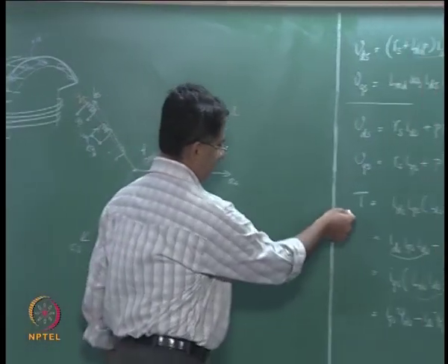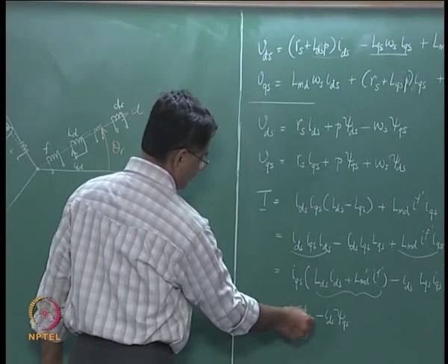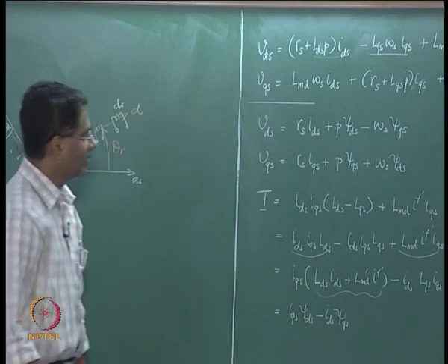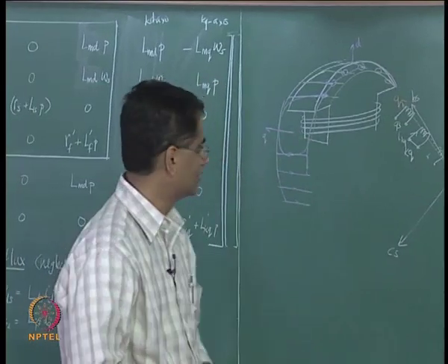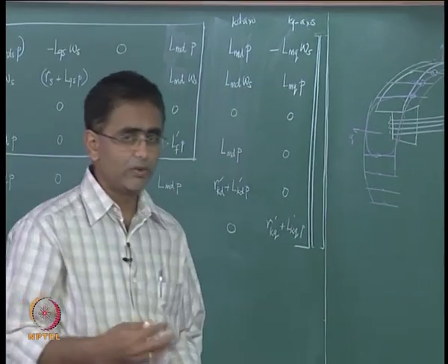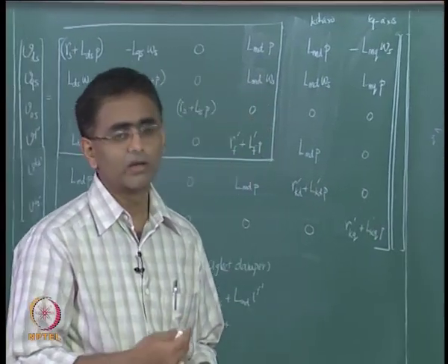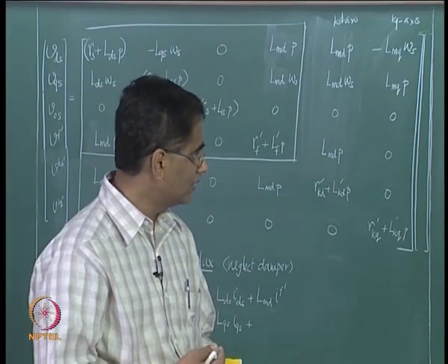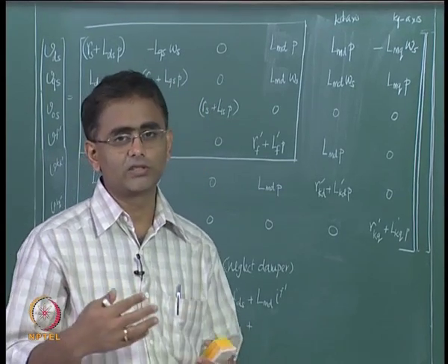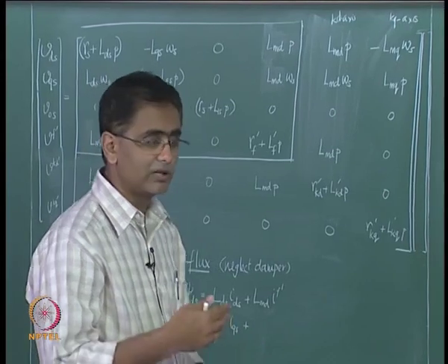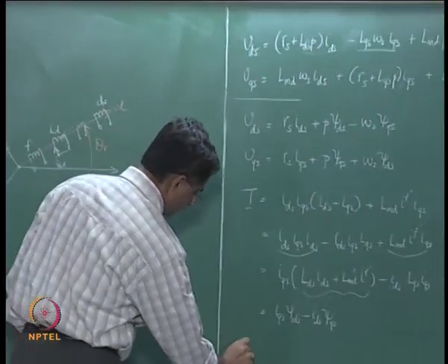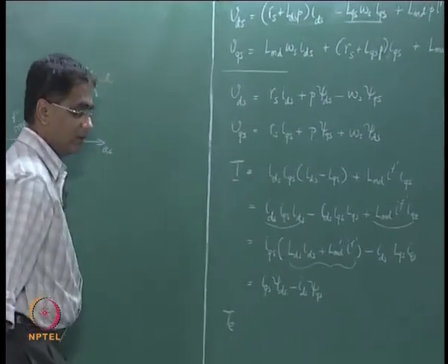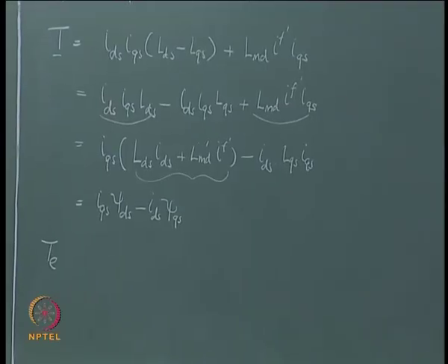So, torque can again be written in terms of product of flux into flow of I. So, these are different ways in which one can represent the synchronous machine equations, which is useful for study. Though we have been representing the electrical equations and the expression for T, in order to describe the dynamics of the system, one must not forget that you need the mechanical equation also, and the mechanical equation takes the form generally, this is your generated torque. Remember, again all the equations that have been written are being written with motor convention.